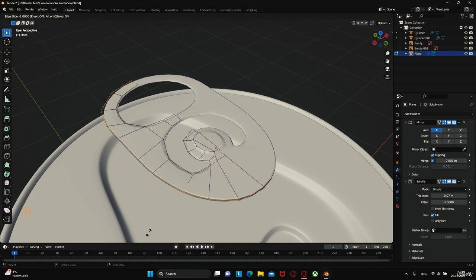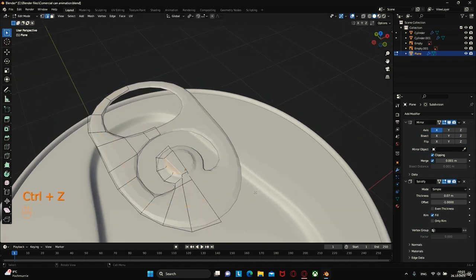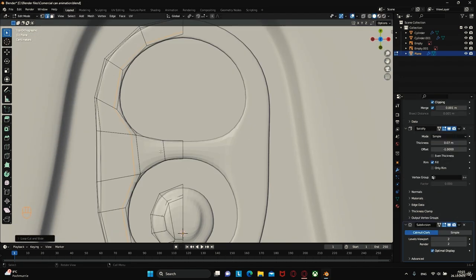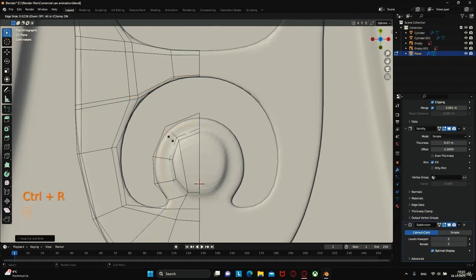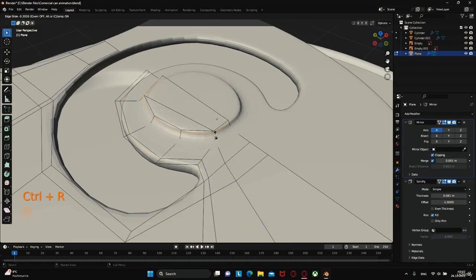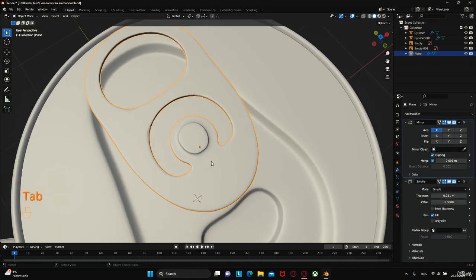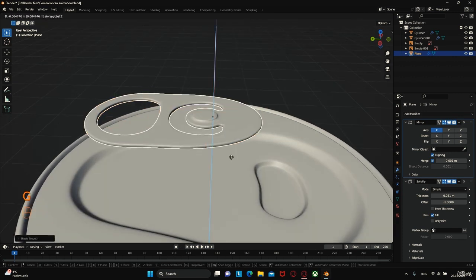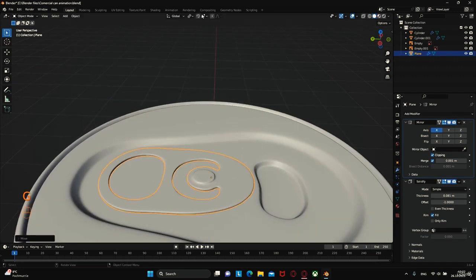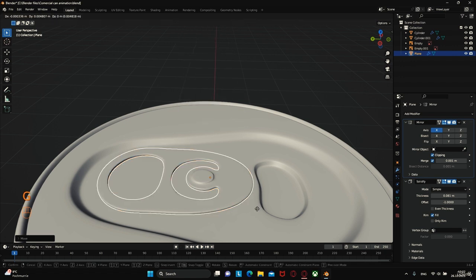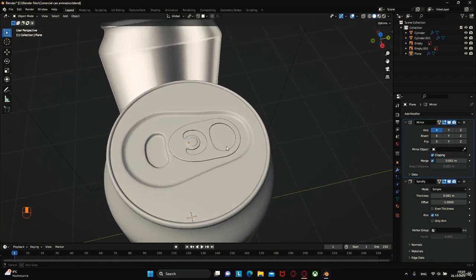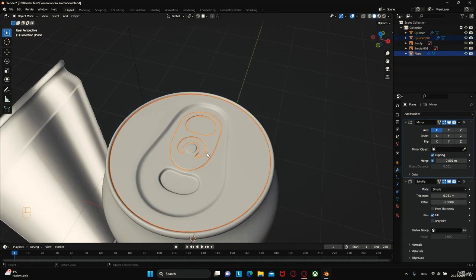And as usual, add them in those places where there are sharper corners. Add one here, and also here. And don't forget to add it here. So in those places where you can expect the edges. And also don't forget to smooth it out in the end. To not struggle with the position, click on this icon and select Face Project. This will allow us to magnetize our object to the nearest face. So select our object and move it along the Z-axis with Ctrl held down.